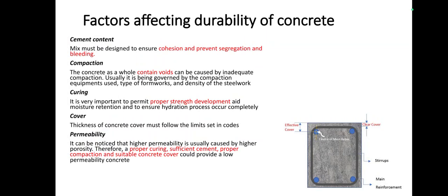In the case of a beam also, the outside face will be exposed to the environment, so the cover depth is only 25, since from the outside face the water may try to enter. Similarly for a column also. For the full length of the column, one side will be fully exposed to the outside environment, so the cover depth for it is 40. When we compare to the foundation, during the rainy season the water table will try to rise, and the foundation has a chance of being submerged in water, so we are providing a cover depth of 75.